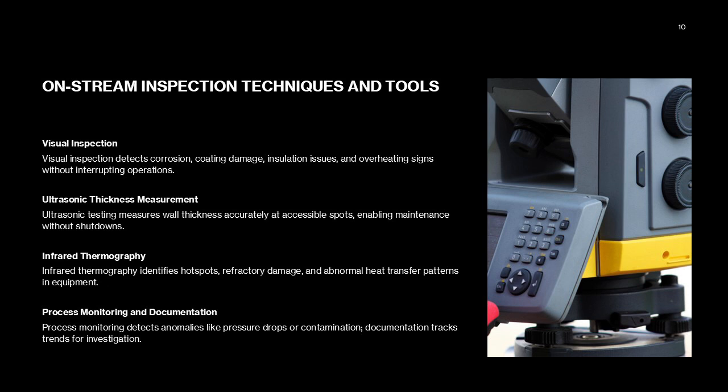Ultrasonic testing is widely used to measure wall thickness at accessible locations without interrupting operation. Infrared thermography can help identify hot spots, refractory damage, or abnormal heat transfer patterns.